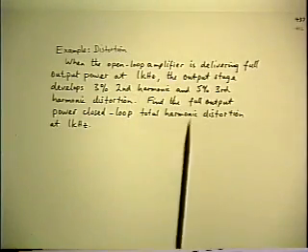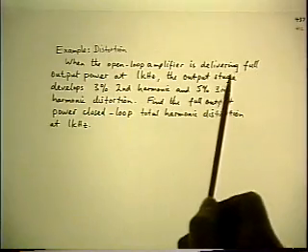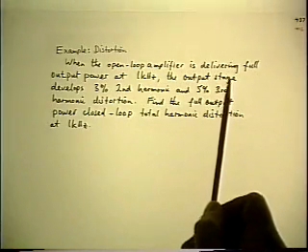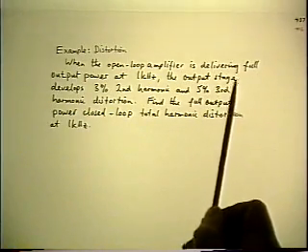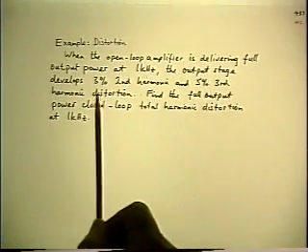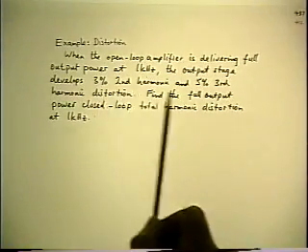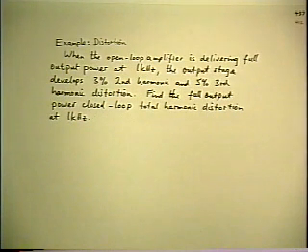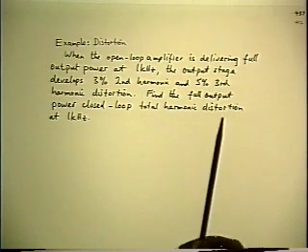So let's suppose, just to pick a starting point, when you drive this little power amplifier to maximum output at 1 kilohertz, for example, let's suppose that it develops 3% second harmonic and 5% third, which you could find out just by measuring it with a wave analyzer or distortion meter. So that's the reference condition.